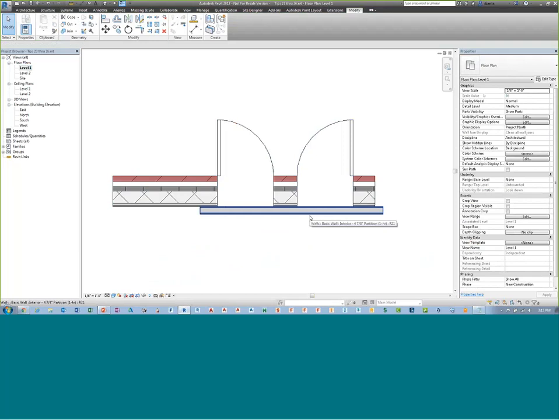Rather than going to an elevation view, looking north of this wall, or starting from here and looking down and using Edit Profile to cut an opening in the wall, or trying to use the door opening family and put it in there, you can just use the Join Geometry command to join this to this, and it'll work. Okay?